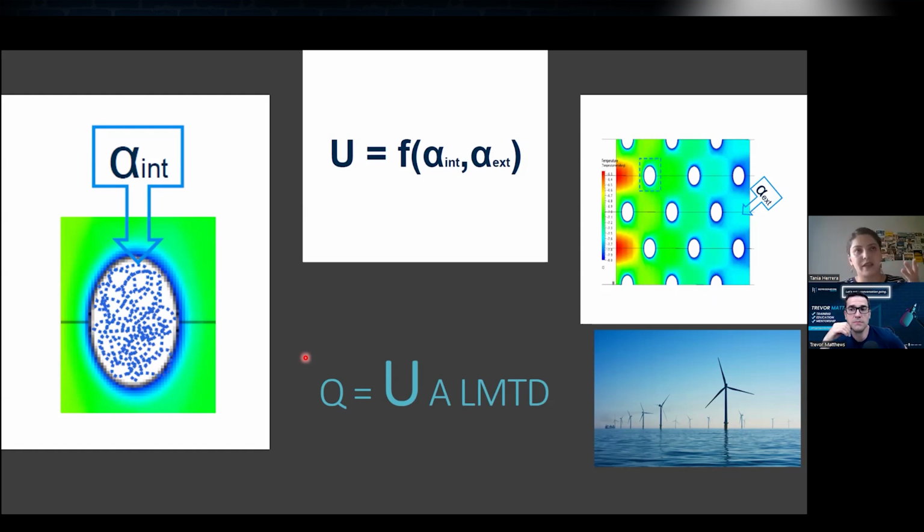But the capacity, if we compare one heat exchanger with coating and one without coating, the one with coating will have less capacity than the other one. Yeah, so in that case, I guess you would have to design it a little bigger. You'd have to have more surface area, for example, with a coated one versus a non-coated one.